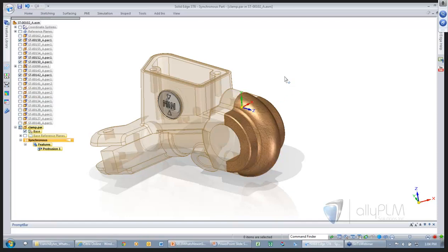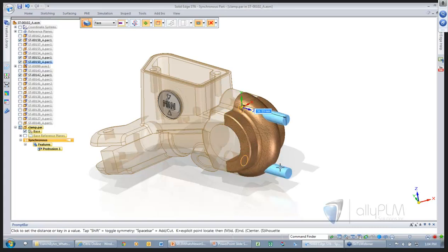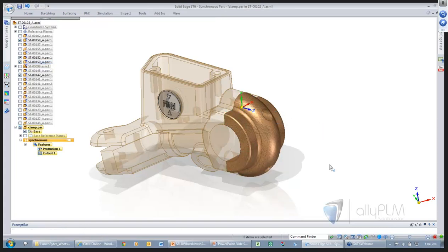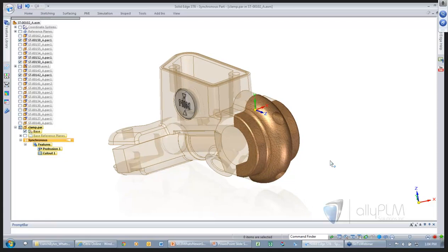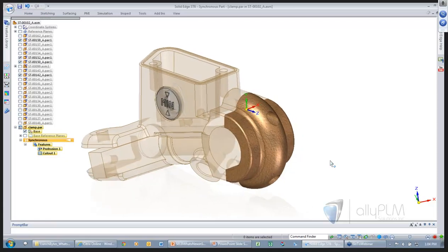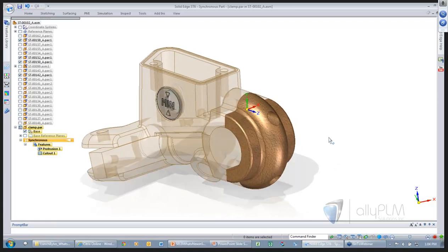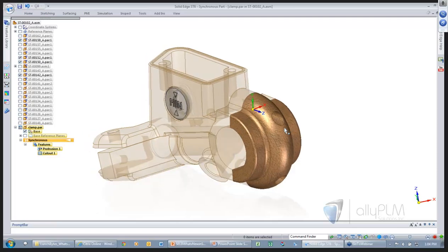Those need to be extruded straight out. So I'm going to go back to Extrude and use only internal loops. So when I grab those faces, I can then pick those and cut those out. I didn't have to go in there and do an include or draw anything or inner part copies just to get to reference. Now I do have a couple of fasteners already sitting in here.